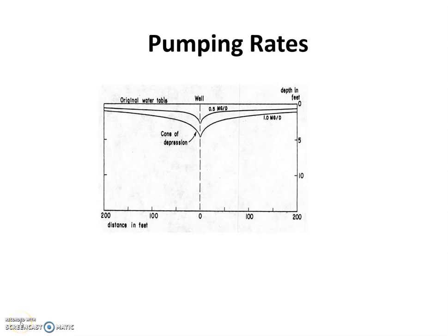I ran out of my free 15 minutes on the first video, so here's the second part regarding Table 1 on page 34 of your lab manual, which is the area required to furnish given quantities of groundwater. We determined that you were interested in the first column, the pumping rate in million gallons per day. The third column is the recharge area in miles squared.